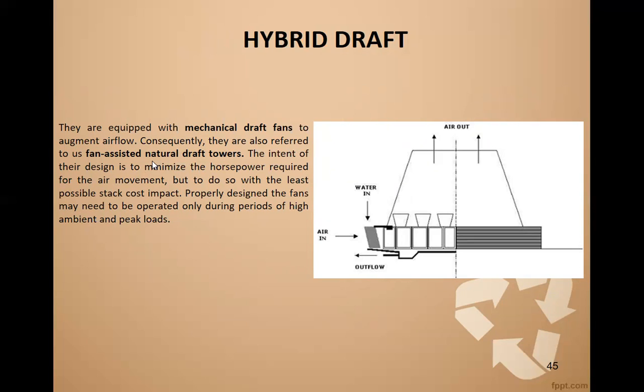Hybrid draft. They are equipped with mechanical draft fans to augment flow. Consequently, they are also referred to as fan-assisted natural draft towers. The intent of their design is to minimize the horsepower required for the air movement, but to do so with the least possible stack cost impact. Properly designed, the fans may need to be operated only during periods of high ambient and peak loads.